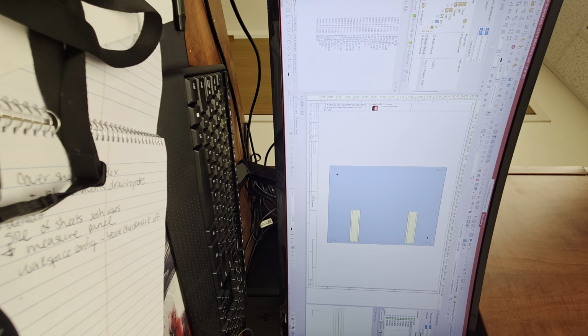So for example, you say, I want to be 1 inch from the left. So 1 inch you already typed in, and then you say align to left. But align to left right now, you don't have a reference as to what. So right now, as we started this selection process, we should have selected your mounting plate and the rail, so the rail knows what is being referenced to, right?